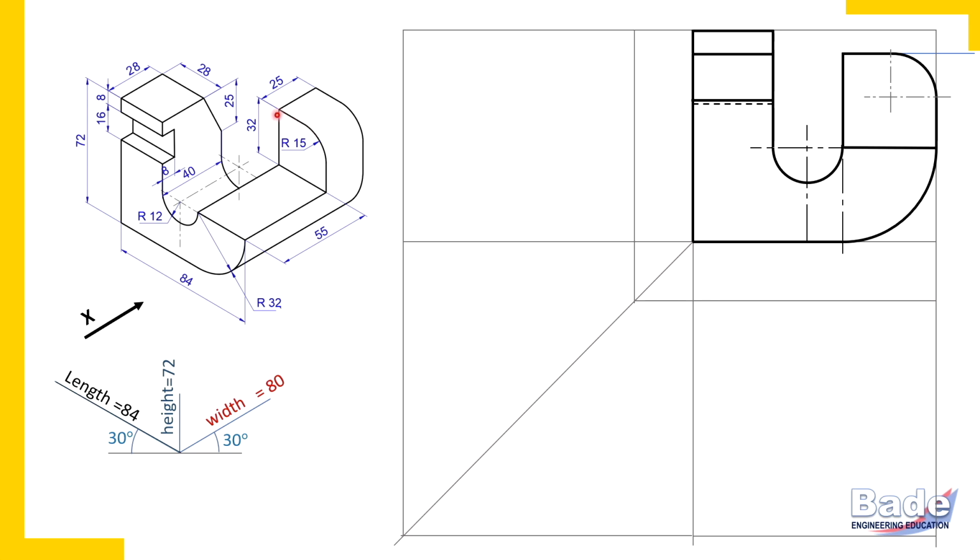Now from this corner there is a vertical edge up to the surface. This surface. Such a surface is not on the back side. So the vertical edge from here is to be assumed up to the base of the object. So from this corner, there is a vertical edge which is visible, we have drawn here.